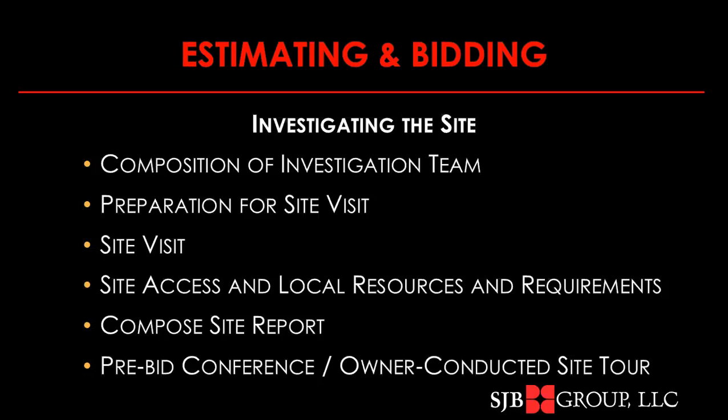While we're preparing for the site visit, we need to identify local sources for weather data, collect some maps and charts of the area, maybe do some research on the tax law and local labor regulations, laws, and rates. We'll need to identify available transportation. We might do some research to pull together some geophysical information. For instance, there's some standard soils reports that the U.S. government did a long time ago, basically for every county in the United States. It's a real good reference for types of earthwork you might encounter.